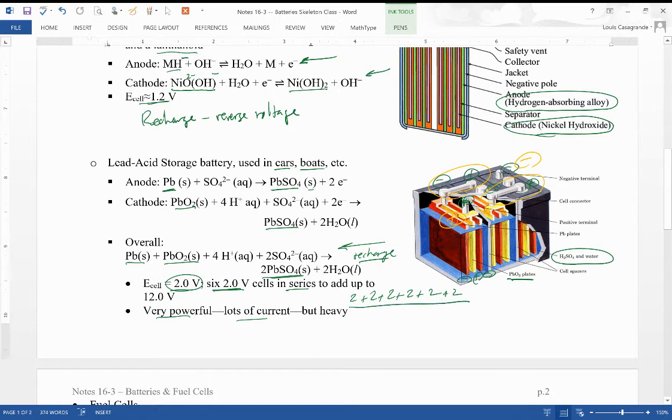You actually do this when you have more than one battery in an appliance. An appliance that needs 2 batteries is actually going to take 2 1.5 volt batteries and make it into a 3 volt. Or you can have 4 1.5 volts, make it into a 6 volt battery. It turns out that 9 volt batteries, those batteries you put into smoke detectors, used to be called transistor batteries because they were the batteries used in transistor radios when those were big back in the 60s.